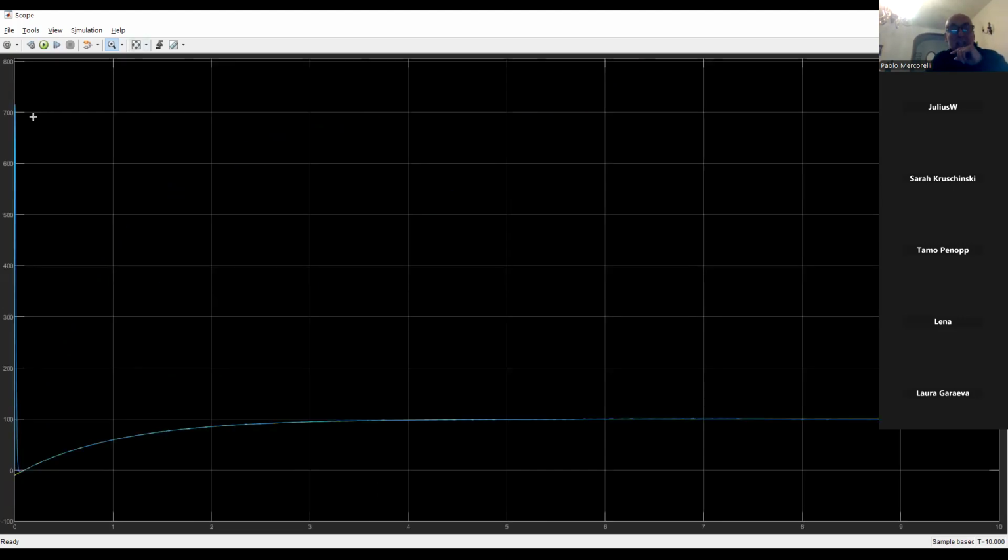Because in order to reduce the initial error, because it could disturb me in control, or to be precise in the monitoring, I have to slow down also the estimation. This is a little bit of playing with this value here. Of course, we will see that the Kalman filter is a little bit easier, I would like to say, to manage this kind of problem, because the Kalman filter is an optimal observer.